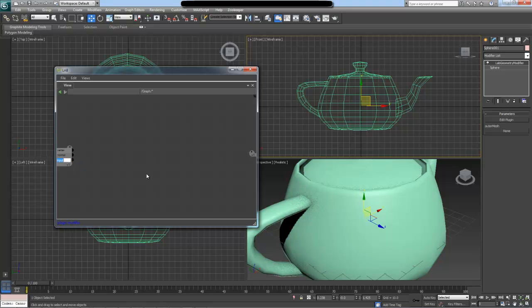So the last thing I need is my outer mesh. And unlike the input that we added for the plugin, I will change the type for this to a triangle mesh instead of a polygon mesh. And the reason I will use a triangle mesh object is because if we drag out its properties, it has this important output called get volume hierarchy, and this essentially provides a way for us to do things like raycasting and intersection testing in an optimized manner without having to deal with every single face.